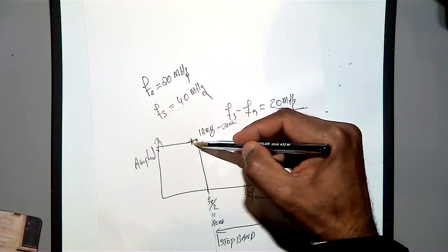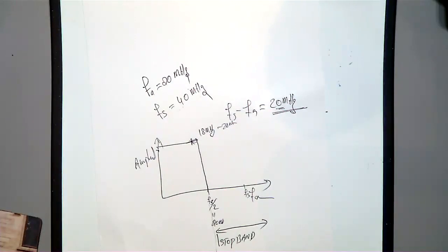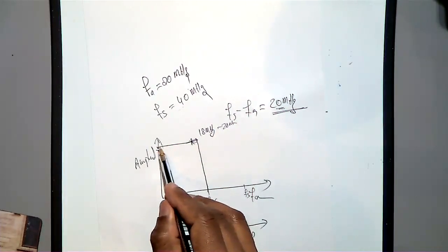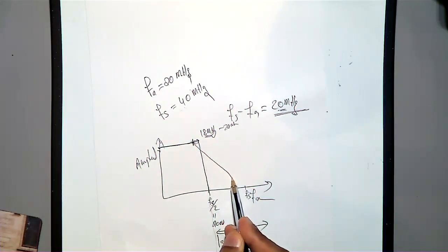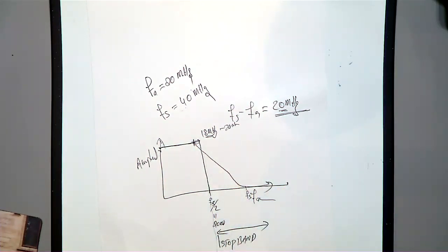That's the reason we said only the 3 dB cutoff. We did not tell you the stop band, because if we specify the stop band, you can't get it. So in your design, you don't have to worry, because you can have 18, maybe 18.5, and let it roll off like this, depending upon your filter order. Still, some high frequencies will be going in. You know what I meant? That is fine. But ideally, in your case, your stop band should start from 40. But that is not possible.